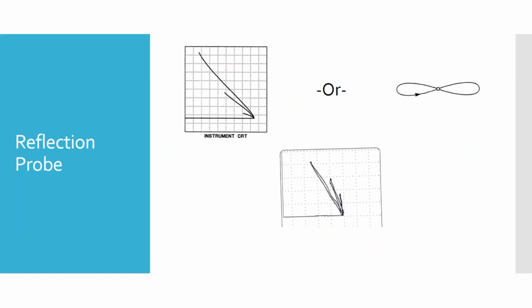And so often the indications will look a lot like an absolute, but in some cases, depending on how the coils are arranged, one above the other, one next to the other, or one inside of the other, sometimes they do the driver coil wound around the outside of the pickup coil in the center, you might get the bow tie, or you may get something similar to the absolute probe, but where it actually creates little loops and lines. So you can see at the end of the day, what you see on the screen doesn't really ultimately matter. You just need to know what you're looking for.